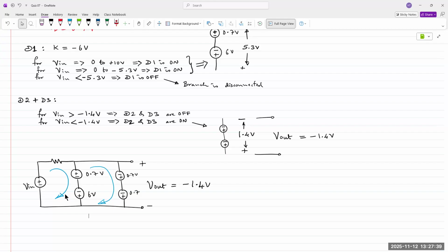It worked in Spice. Sorry. I ran the simulation in Spice and it worked. But Spice does not use CVD models; it uses real diode models. So the voltage does come out to be constant across both the branches, but it comes out to be about 3.9 to 4 volts.